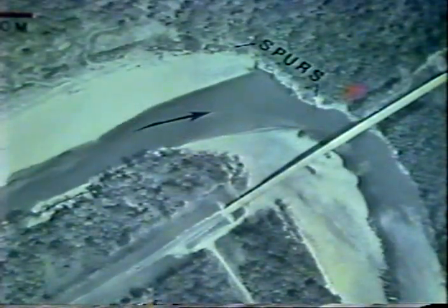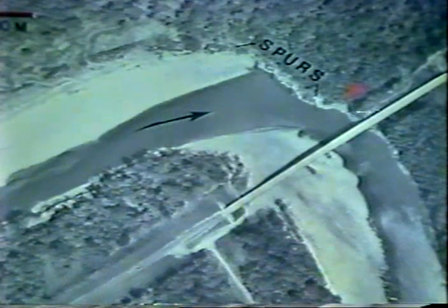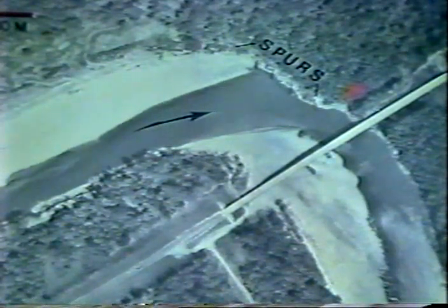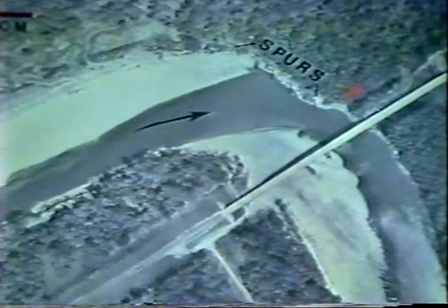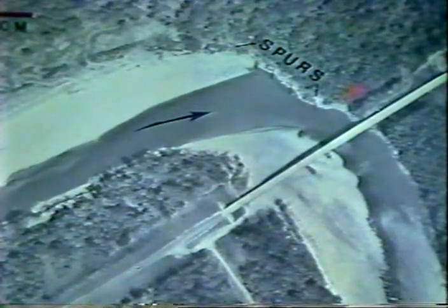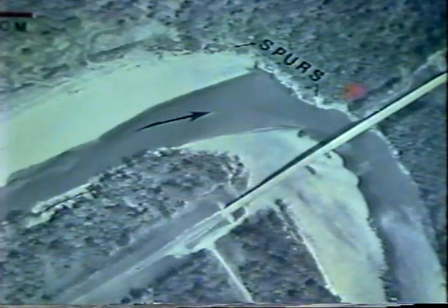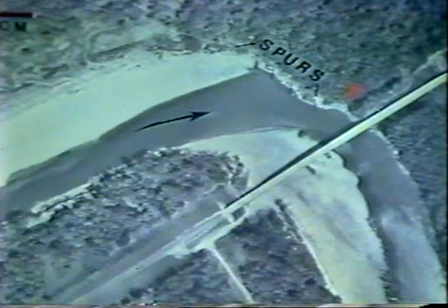Spurs may not be effective for flow control at a sharp bend near the bridge. At this difficult crossing situation, bank erosion, shown at the orange marker, has occurred downstream from 5 timber pile spurs, and the channel has continued to migrate laterally. Additional spurs or a retard may be needed just upstream from the bridge.